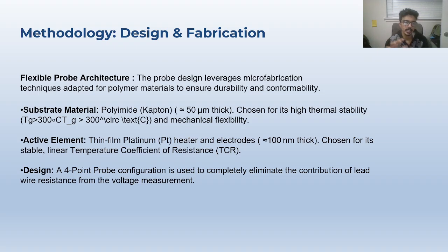The substrate material will be made using polyimide, which is Kapton, which I mentioned earlier, and the thickness has to be close to 50 micrometers. And we have used polyimide because of its high thermal stability and mechanical flexibility, which is what we want from that probe, for it to be flexible.